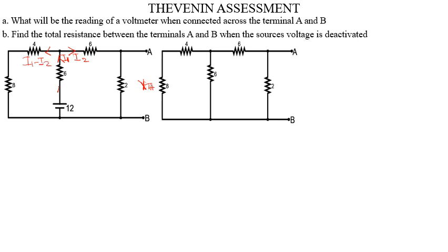After doing this, we've now analyzed our circuit. All that is left for us is to apply KVL and KCL. I'll first apply KVL in this first loop, and I'll take my direction as anti-clockwise. Applying KVL in this left hand side loop, we get the voltage source. We are moving from a lower potential to a higher potential, so it's positive 12 volts. Then we meet this resistor, and the current flowing through it is I1, so it becomes 6I1.